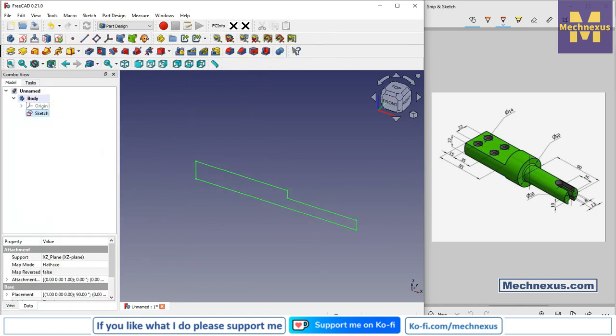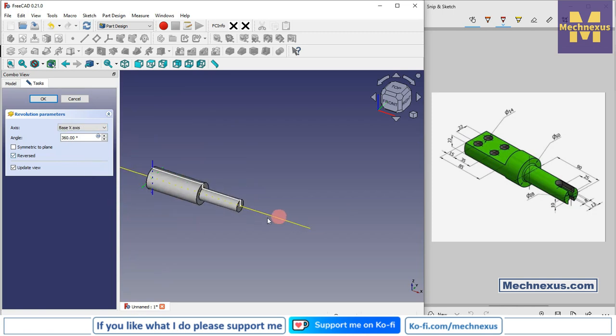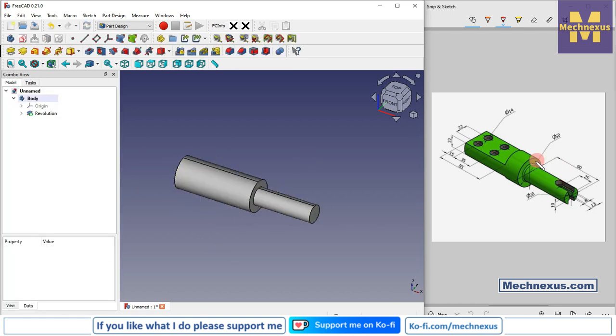And now we will use the revolve tool. So click on the revolve icon, and here select reference, and we wanted to revolve it around the x-axis. So we will select this x-axis and click on OK. So we have created the base profile, and now we will do the material removal operations.